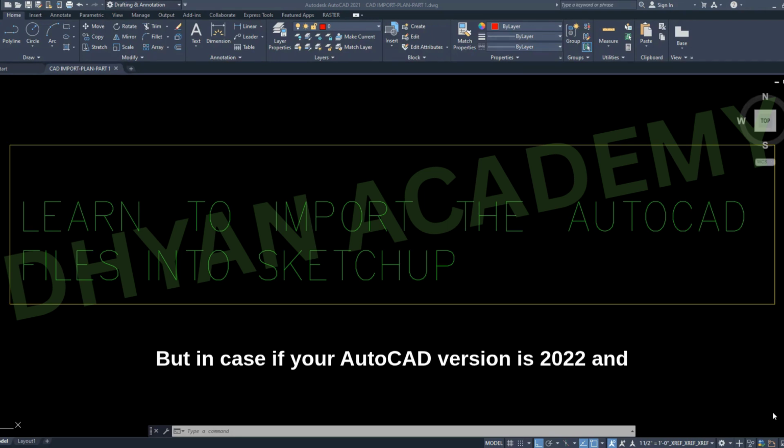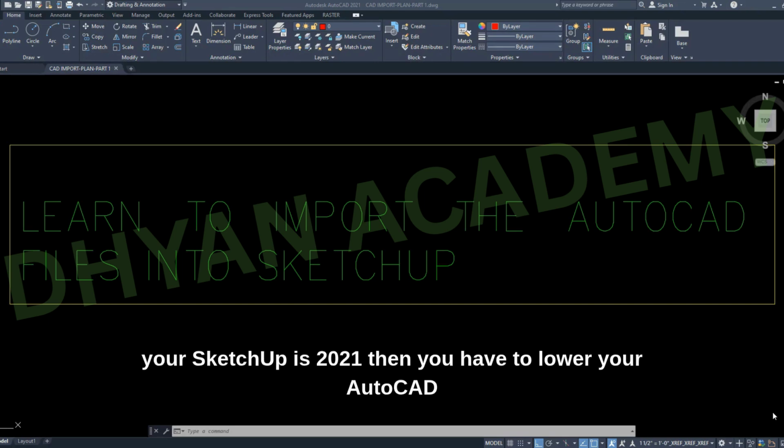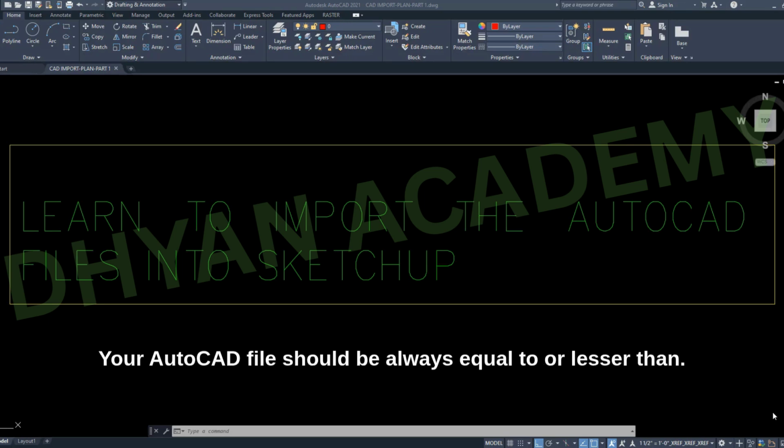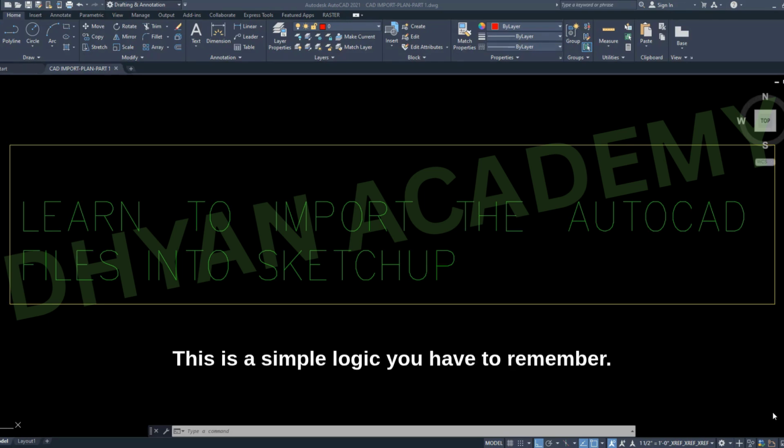But in case your AutoCAD version is 2022 and your SketchUp is 2021, then you have to lower your AutoCAD file version before inserting into the SketchUp software. This is the first rule that you have to remember. Your AutoCAD file version should always be equal to or lesser than your SketchUp version. This is the simple logic you have to remember.